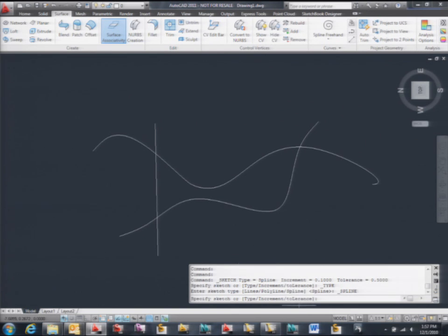And it has two options called increment and tolerance. The increment is a distance which, when you make the stroke, right? Let's say this is a building, and that stroke is the whole base of a convention center here, and it's, I don't know, 300 meters, half a mile, whatever this distance is. If you do that, you probably don't want one point recorded after every meter. You want something every 20 meters, 30 meters, 40 meters, right? So then you would insert 40 before starting.